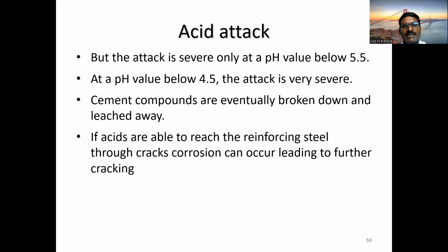The acid attack is severe only at a pH value below 5.5. If the pH value is below 5.5, then the acid attack will be there, and it becomes more severe as the pH value goes below 4.5.